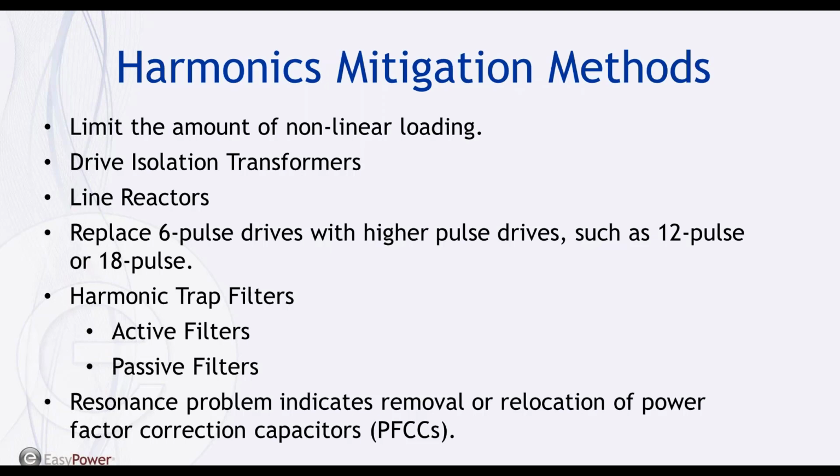Well, of course, we could limit the amount of nonlinear loads, but this is typically not an option with the necessity of these loads with limited resources. Line reactors and motor drive isolation transformers use reactive harmonic attenuation effects to reduce the actual current distortion at the input terminals to the drives. Line reactors are more commonly used because of their size and cost. As we discussed earlier, we could replace 6-pulse drives with higher pulse drives, such as 12-pulse or 18-pulse drives.